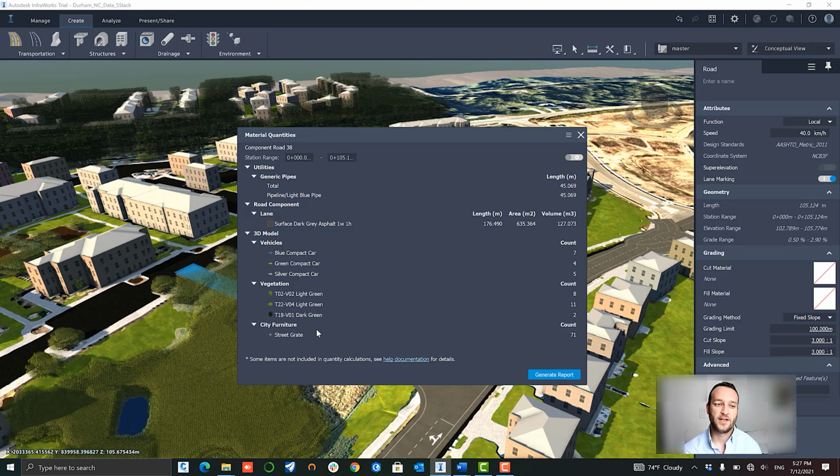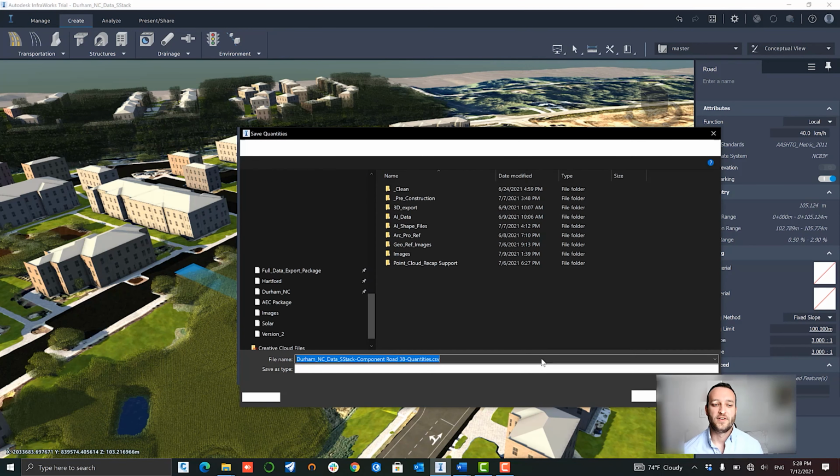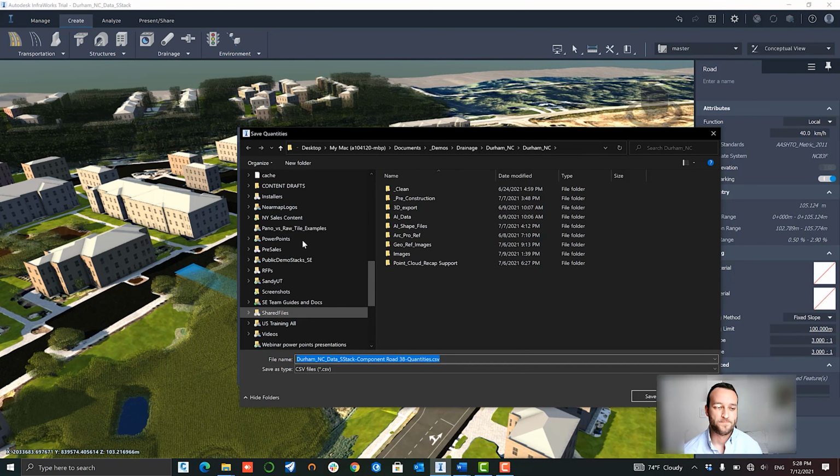You can see that in the 3D model layer here, anytime that an AI attribute that we have created, has been imported from Nearmap, is being intersected with the new proposed roadway, it's going to be reflected in that material takeoff estimate. So it's going to help identify ground features that are intersecting and interfering with any new proposed design. So that's things like vegetation, interference with existing utilities, which types of ground features, like if you're already hitting existing concrete or asphalt, what sort of costs need to be reflected when bidding that job.